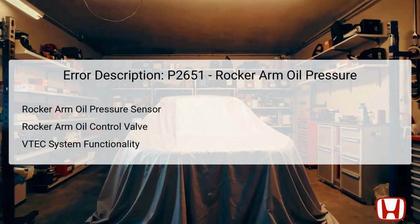The primary role of this sensor is to provide feedback to the PCM about the oil pressure status, which is crucial for the operation of the VTEC system. If the recorded oil pressure is low, the PCM may interpret this as a fault condition and store the DTC P2651. The rocker arm oil control valve manages the flow of oil to the rocker arms, impacting how well the engine performs, especially during variations in speed and load. This entire assembly is integral to the engine's performance, and accurate pressure readings are necessary for efficient engine operation.